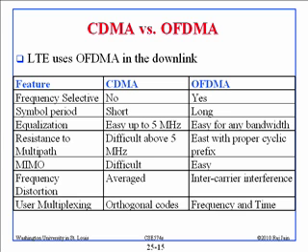Symbol period: the bits are very short. Actually, in CDMA the chips are shorter than the bits, because instead of bits we transmit chips. So there is a lot more interference. Well, it's not symbol interference, it is chip interference. Each bit is a symbol, or it could be even more. So the symbols are short. Here the symbols are very long because we have only 10 kilohertz. That's the advantage of having 10 kilohertz. 10 kilohertz symbols are big, 15 kilohertz symbols are smaller.